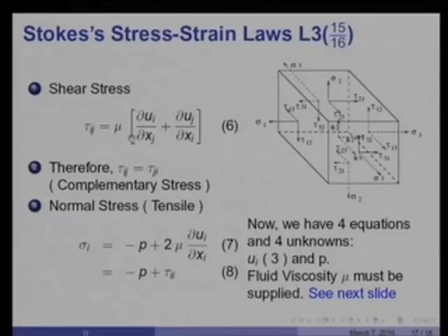But there are fluids like blood or polymers and so on, in which the magnitude of viscosity itself depends on the rate of strain, and sometimes on the manner in which the fluid was strained through time. And therefore, viscosity also happens to be a function of time, a function of the flow in which the fluid is situated, and so on and so forth.